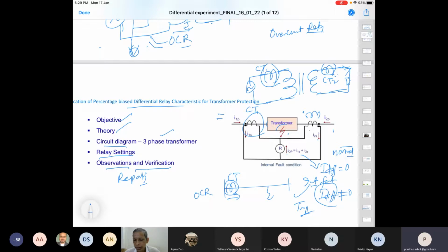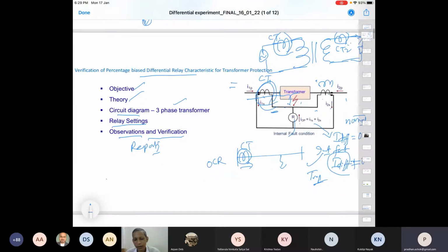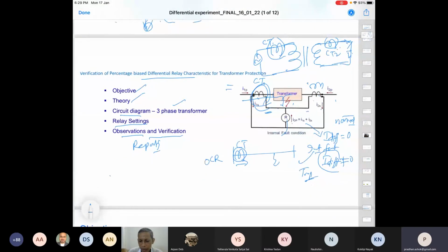Then whenever an internal fault happens, you can check and see that the differential current flows here, and the differential current may not be flowing on the other side. So this side will be large current, this side will be no current. Therefore this current will be significant. That is your first check. Agree? This is a requirement from the connection perspective.